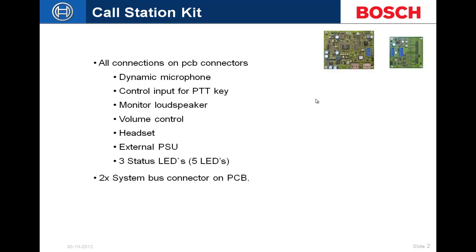This has an external power supply connector, so we have the ability to power it externally, meaning backup power, versus our normal call stations, which don't have that external power on them. This is going to give you the ability to have remote power basically for that. 3 status LEDs are essentially on the board itself, giving you the fault and call notifications as well as emergency notifications right on the board itself, with LEDs plugged into the header basically.